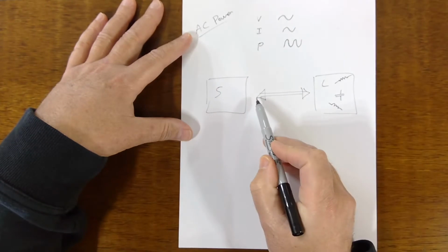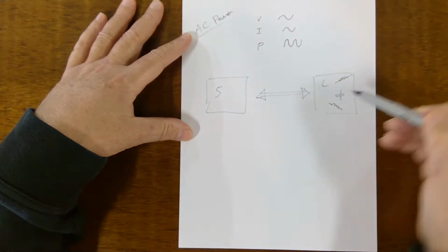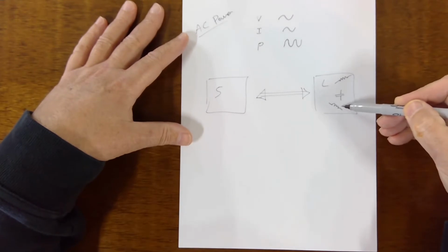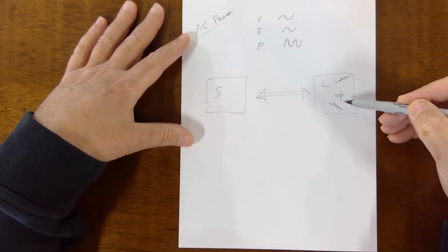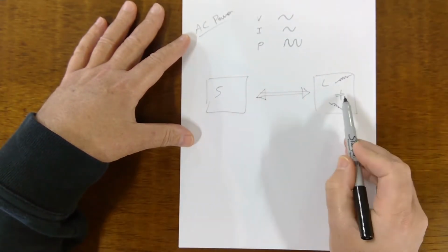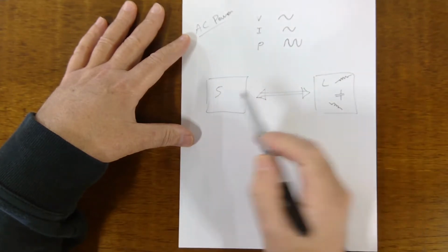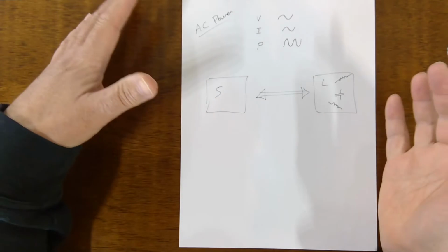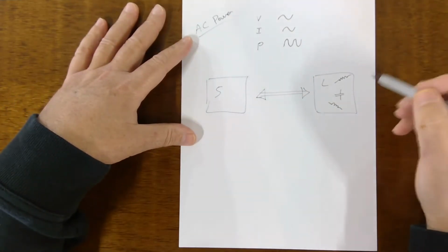It's kind of like a little tug of war. The power goes over here and then it comes back, because a capacitor and an inductor are storage devices. So a lot of the power is going to go into these storage devices and then bounce back, okay? And that doesn't really do you any good, just playing this back and forth thing.